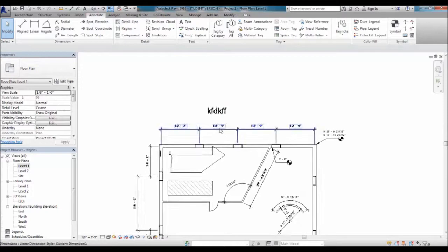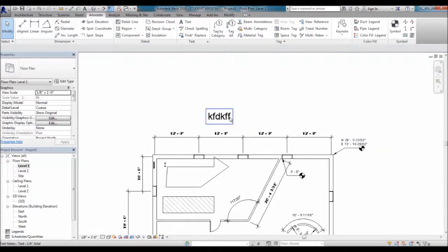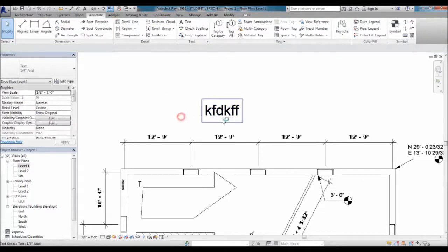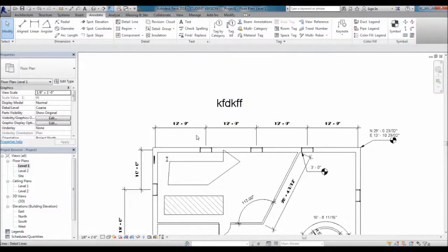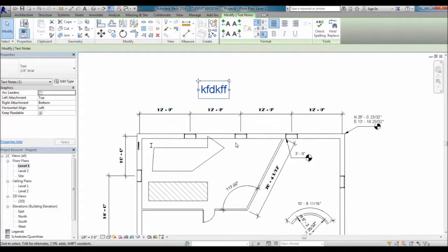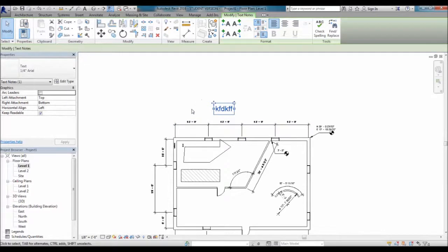That's a bit larger than this text here that I have for my dimension lines. But because you have this set at quarter inch, that's going to print out at a quarter inch. So when you're looking at this view, where an eighth inch equals a foot, that's how large that quarter inch text looks in relation to the rest of your building.